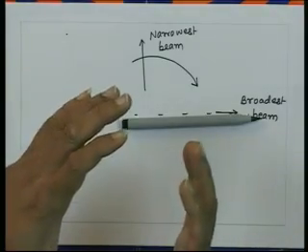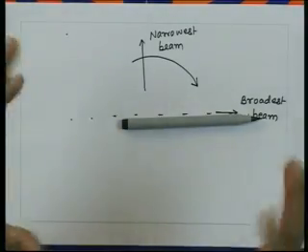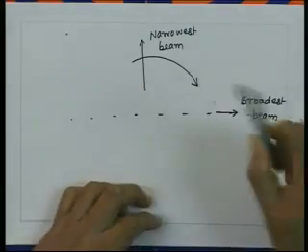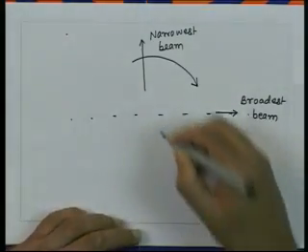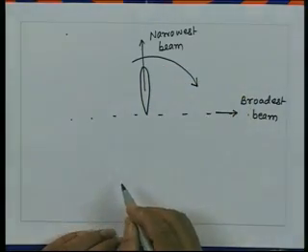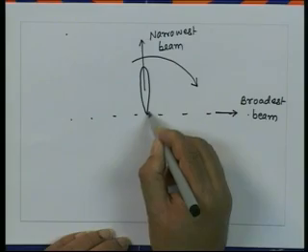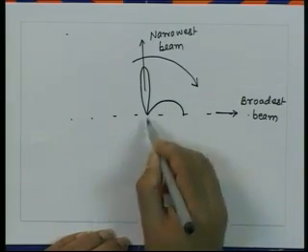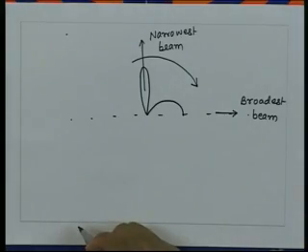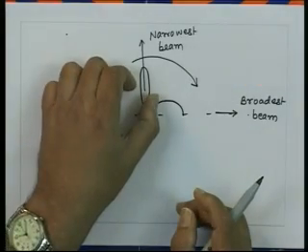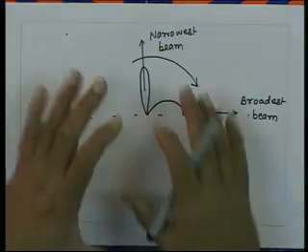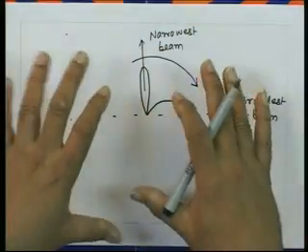Visualize this radiation pattern as the beam is scanning in 3 dimensions, and in fact they have totally different appearances. If I consider the planar radiation pattern, the beam width will be narrow here, something like that. When it comes here, it will be broader, so it will look something like this. Similarly, when it comes on the other side, it will look broader like that. So, it looks as if the beam simply is broadening, otherwise the pattern practically remains the same. That is the appearance you get from the planar radiation pattern.